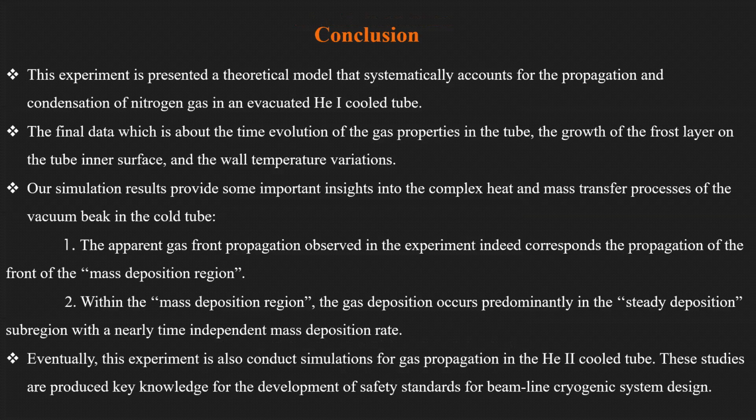And at the end, in the conclusion, the experiment presents a theoretical model that systematically accounts for the propagation and condensation of nitrogen gas in an evacuated helium 1 cooled tube. Our simulation results provide some important insight into the complex heat and mass transfer process of the vacuum break in the cold tube. The first is that the apparent gas front propagation observed in the experiment indeed corresponds to the propagation of the mass deposition region. In the mass deposition region, the gas deposition occurs predominantly in the steady deposition subregion with a nearly time-independent mass deposition rate.